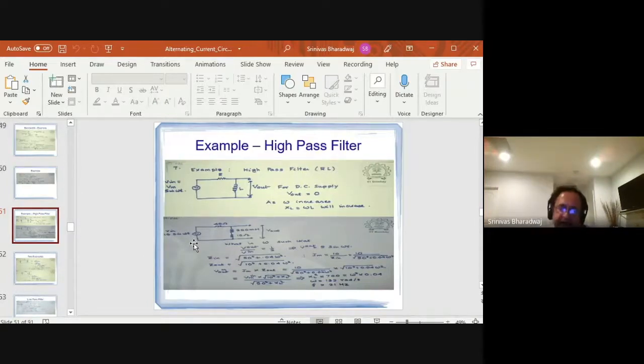In a DC circuit, a capacitor will behave like an open. It will act as though there is no connection. If you just attach a capacitor to a battery, right? It will just charge the capacitor, and then eventually, in steady state, there will be no current. Okay. Now the inductor is the exact opposite. In steady state, the inductor will act like a short. Okay, like a short circuit. You will have almost like there is no resistance, in the case where you connect it to a DC voltage.